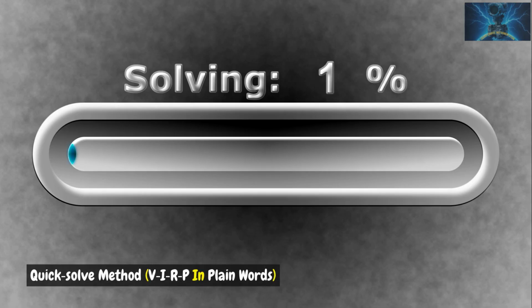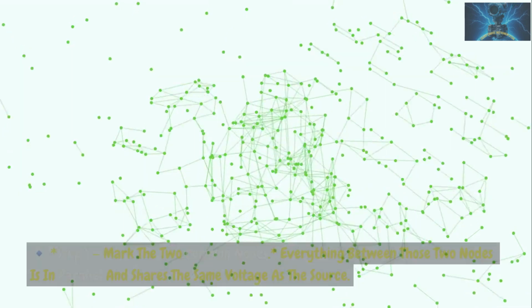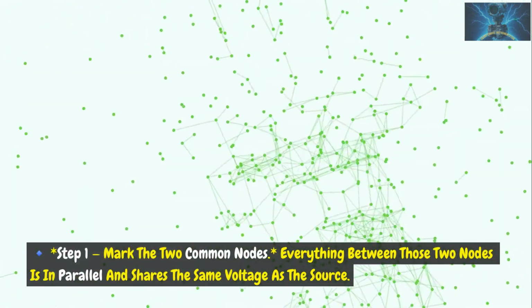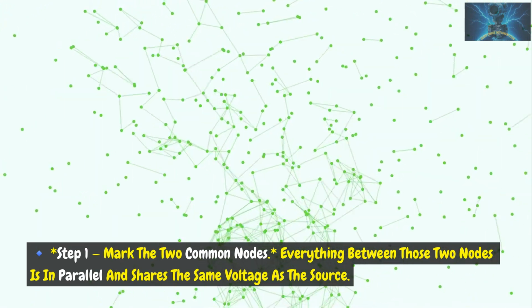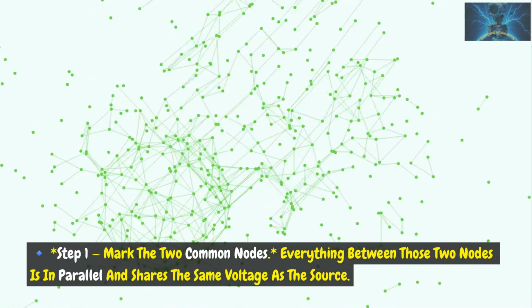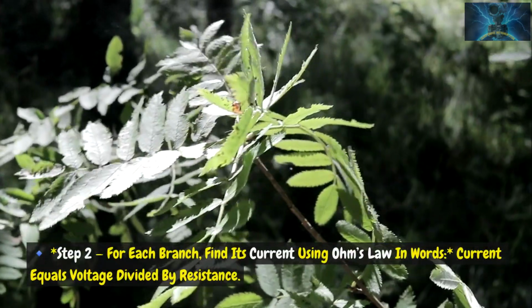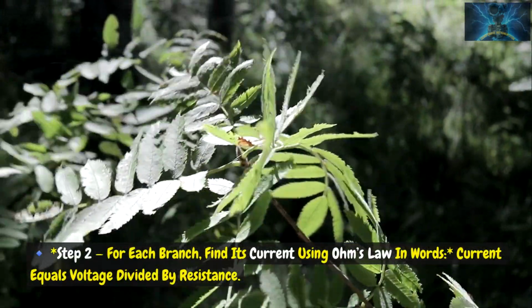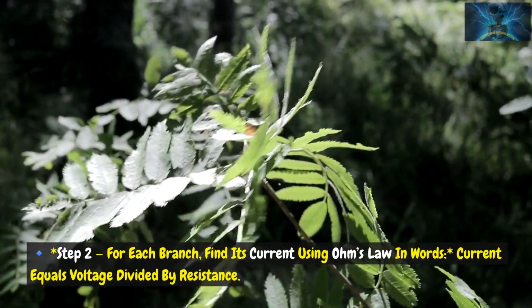Quick solve method, VIRP in plain words. Step 1. Mark the two common nodes. Everything between those two nodes is in parallel and shares the same voltage as the source. Step 2. For each branch, find its current using Ohm's law in words. Current equals voltage divided by resistance.